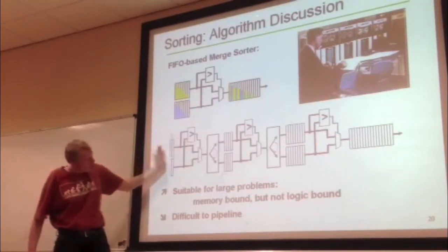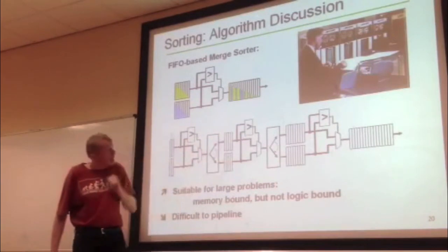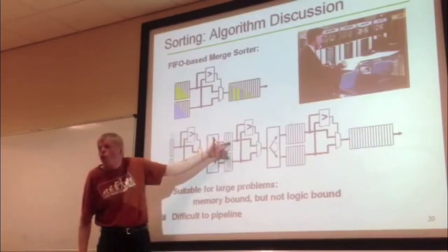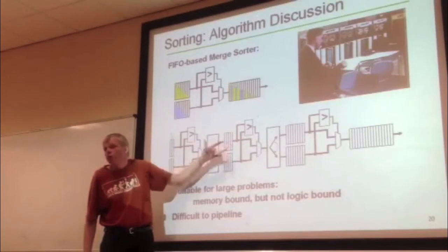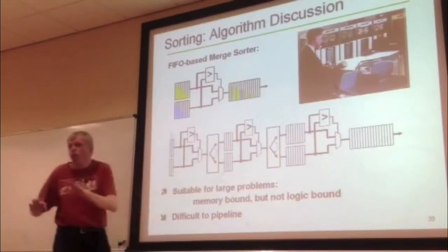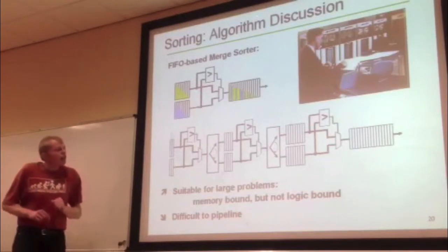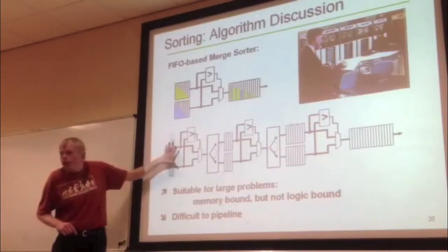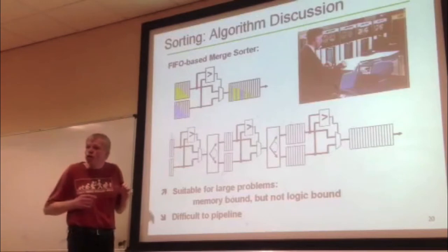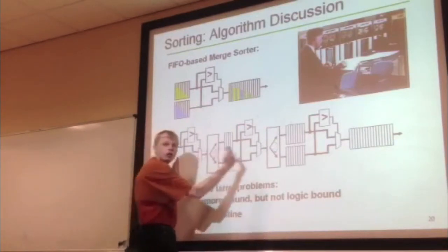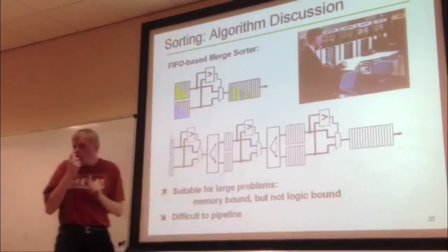So this whole thing works with 2 gigabytes per second. And there are some tricks how you use this memory, how you build this memory structure, do the data movement. I don't want to go into detail because you would get it not in your brain. But that's how you can implement a sorter in a pipeline fashion. And this fits very well to an FPGA.